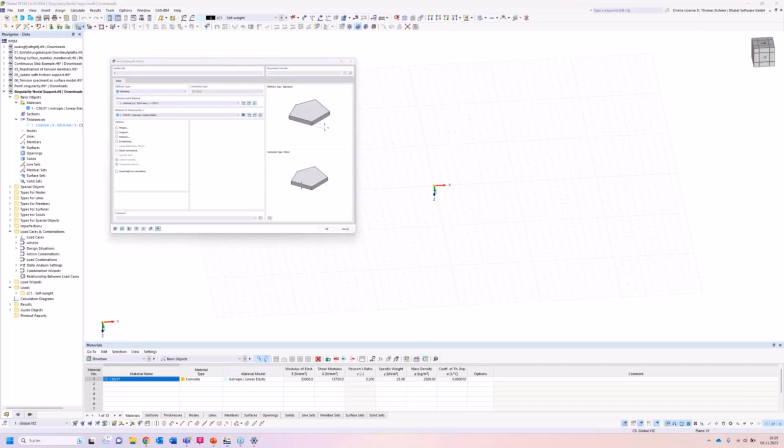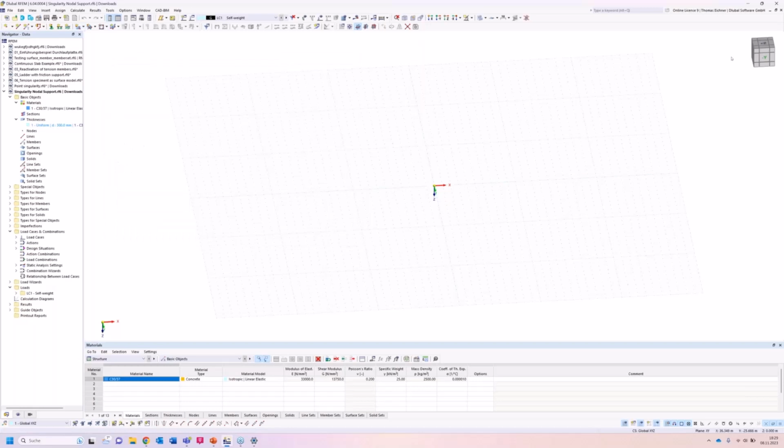Okay, this time I will go out of this dialog again. I want to go in this Z view via cube. So I will go on this cube and press on this plus Z. You can also throw around your cube however you want, but we will stay in the Z plus direction.